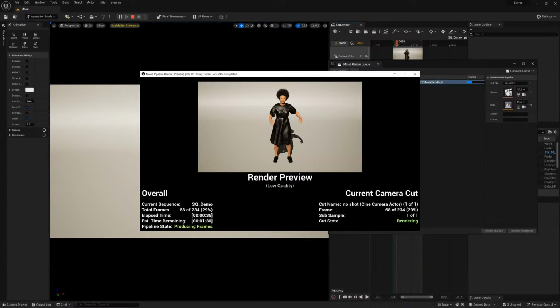Yes, it is. And also, if you wanna save time, you don't need to go with a high quality image for generating cache. You can just use 100, 105. But depending on the complexity of your clothes and avatar, it's gonna take about a minute. For example, this motion is about 234 frames, and it's gonna take about 1 minute. I think it's quite fast to generate cache.